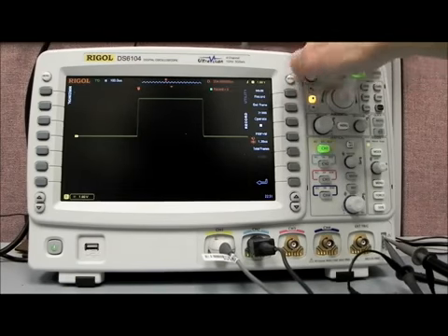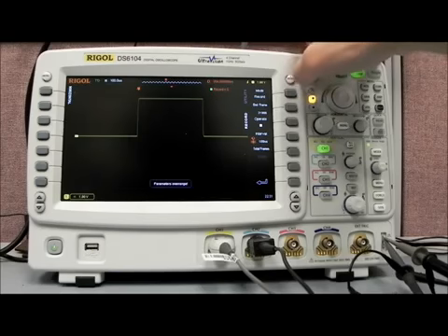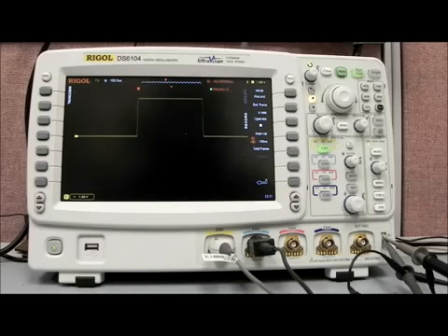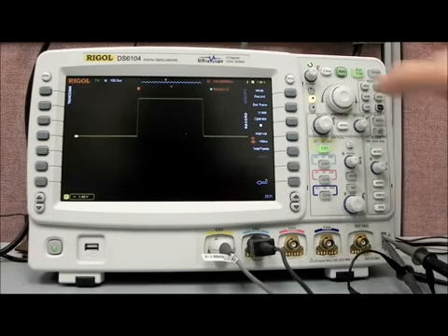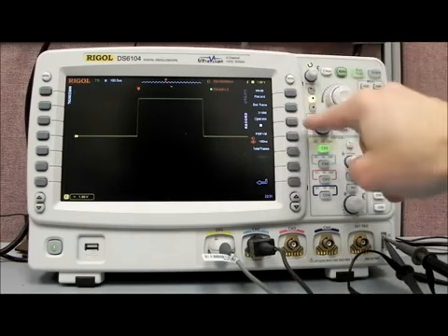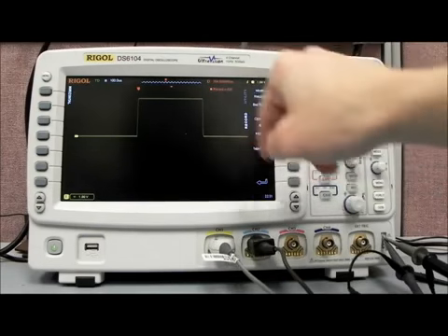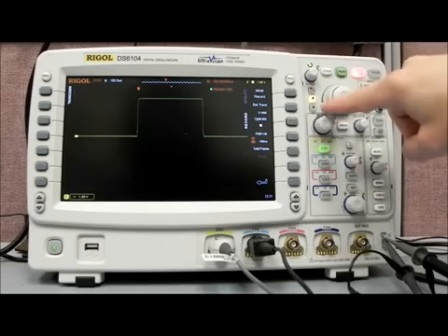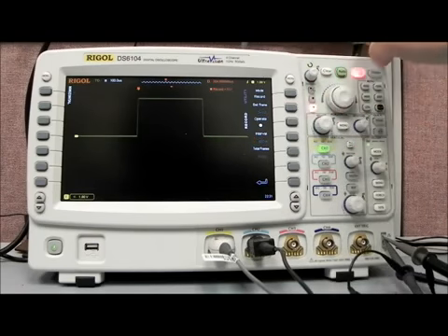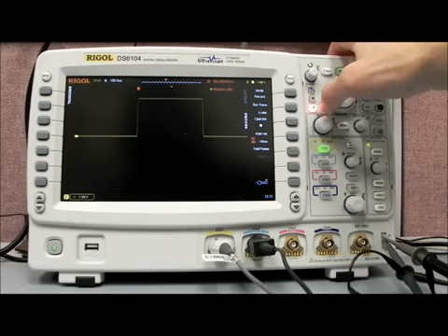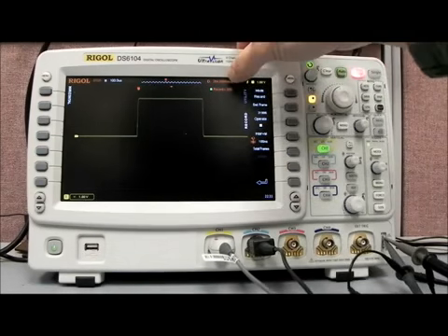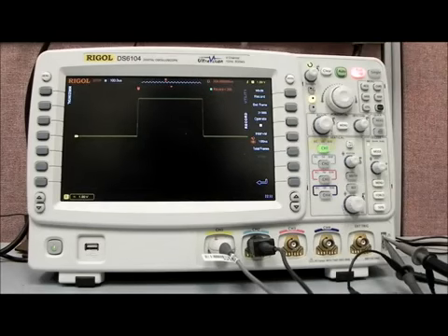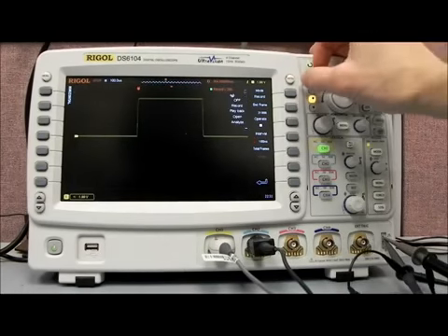We can go all the way up to, I believe, tens of seconds if you wanted to do that between frames. Typically you're going to want the recording to be as quick as possible because you want to basically create this giant movie of all of these different frames of data. To record, very straightforward, we can press the operate key and you'll see we start to collect. We can also stop it, or even better, use the record and stop buttons in this Ultravision area. So you see we've collected 280 waveform recordings.